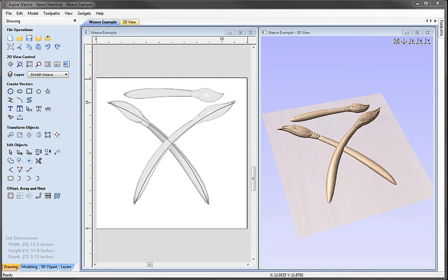We also looked at how rather than using a vector cross section, we can import a 3D component and extrude that along our vector drive rails as well, either so it repeats or as an individual object that's stretched all the way along the full length of the line. We finished off by looking how you can take all these shapes a step further by using the weave option in the function. That concludes this video.